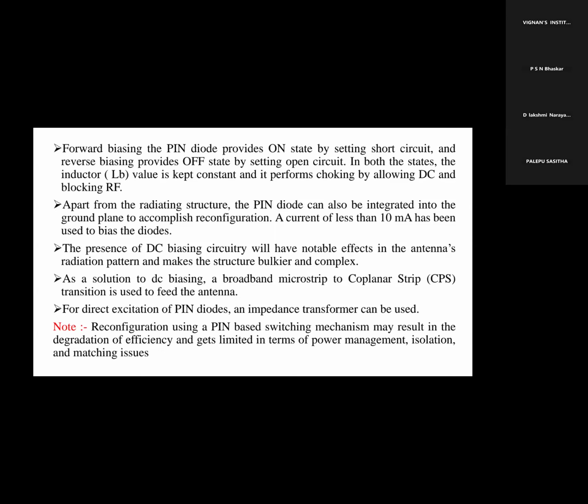One of the drawbacks of reconfiguring using a PIN diode switching mechanism is that it may result in a degradation of efficiency and be limited in terms of power management, isolation, and also matching issues. These are some of the drawbacks of using a PIN diode as an on and off switching mechanism.